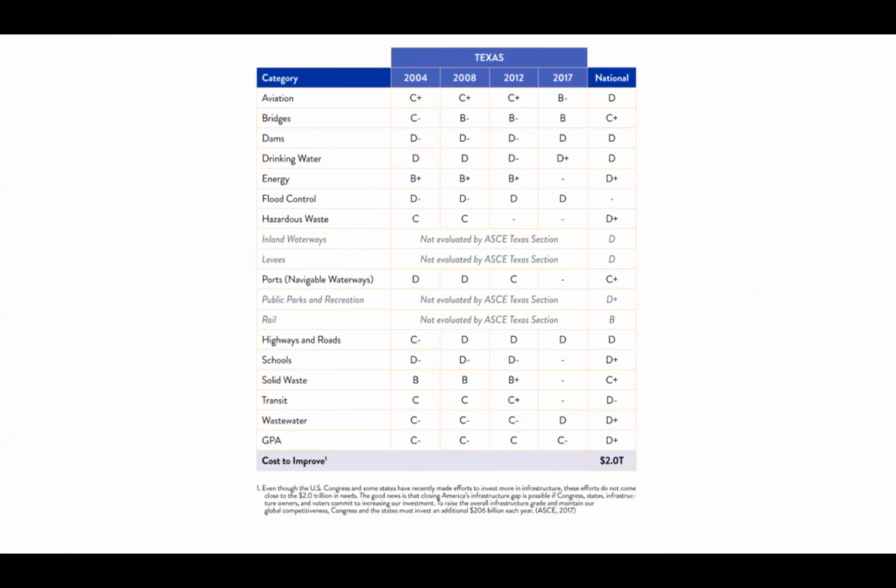NDE is not used currently in routine bridge inspections. Mainly visual inspections may not be sufficient to assess the overall conditions. Any thoughts? That's true. A routine bridge inspection, which is done every 24 months, is typically just visual in nature. However, items of concern are flagged, and in an in-depth inspection, which would be a follow-up inspection, NDE is commonly used to further investigate.